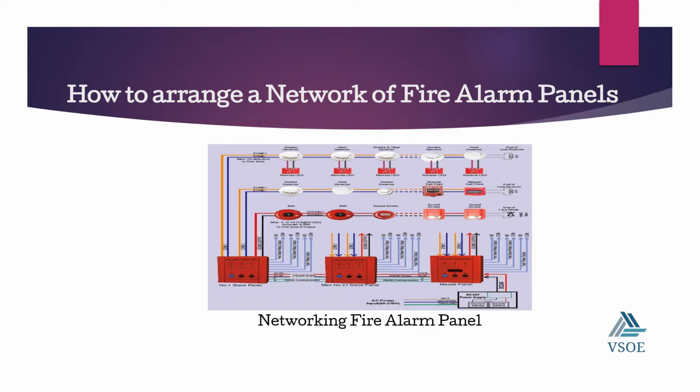The next thing we're going to look at is how one can arrange the network of the fire alarm panel. So fire alarm panels are networked based upon the fact that we can increase its reliability in operation. And secondly, we must understand that each panel works independently.